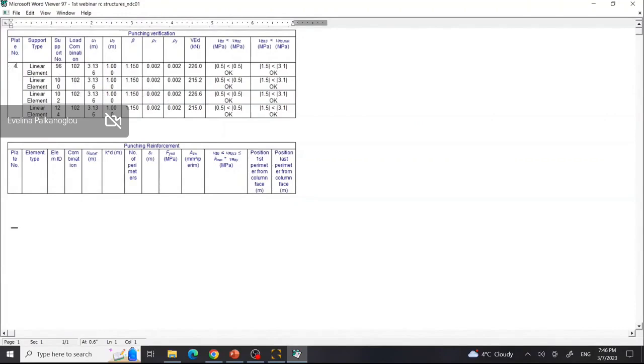So you see these elements. As you can see here, the element has the plate, the punching shear effect on the plate. Then you see all those different parameters creating this punching shear effect on the planar element, and they are all used in the Eurocode parameters that the Eurocode requests to define the parameter and calculate the area in order to deal with punching shear.